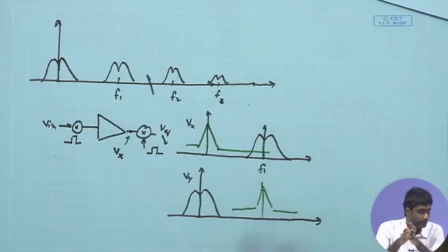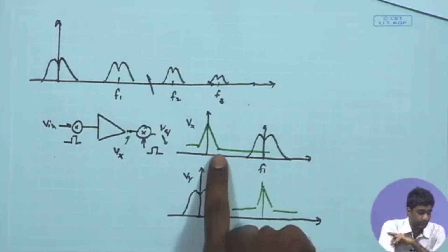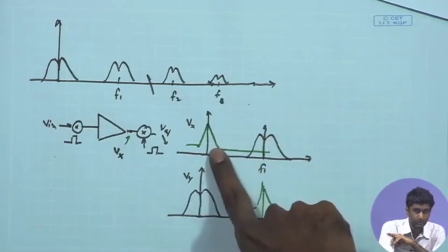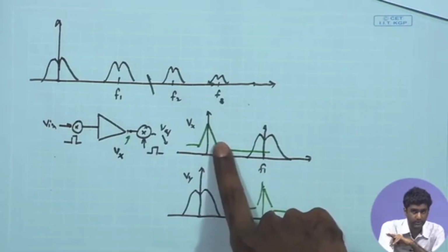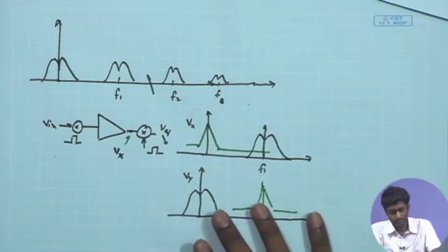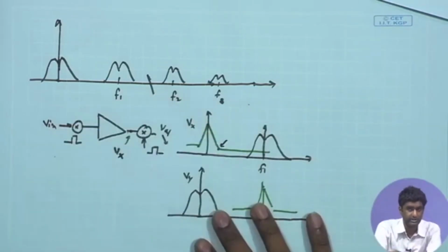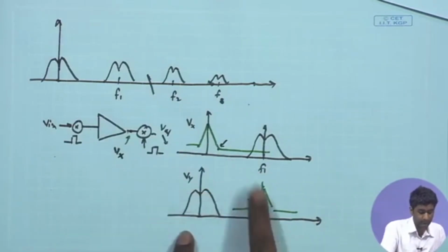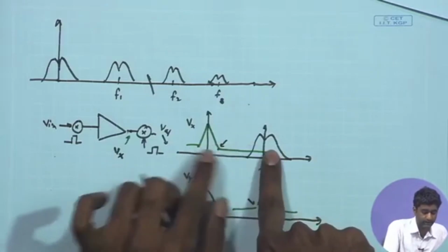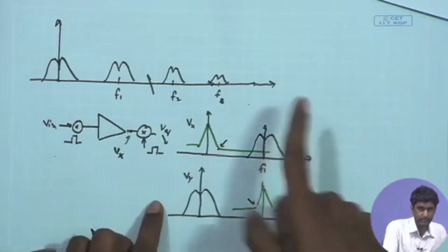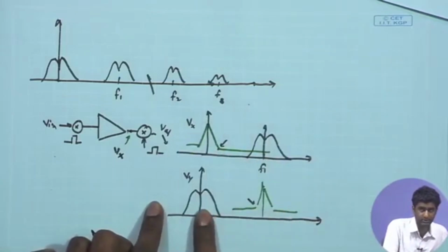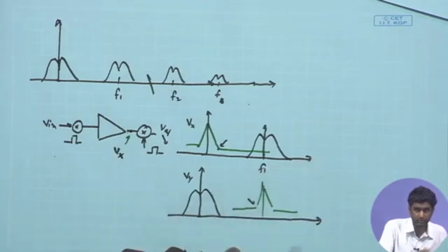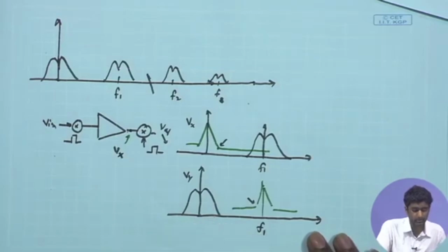What should be the chopping frequency? One of the criteria that we always have is this 1/f noise corner, and we would like our signal to be sufficiently higher than this 1/f noise corner, so that it is not affecting our signal. So, the obvious answer at first hand is that it should be sufficiently higher than this corner frequency, so that after the anti-chopping process the desired signal is coming back, and the 1/f noise spectrum is shifted to a much higher frequency given by the chopping frequency f1.